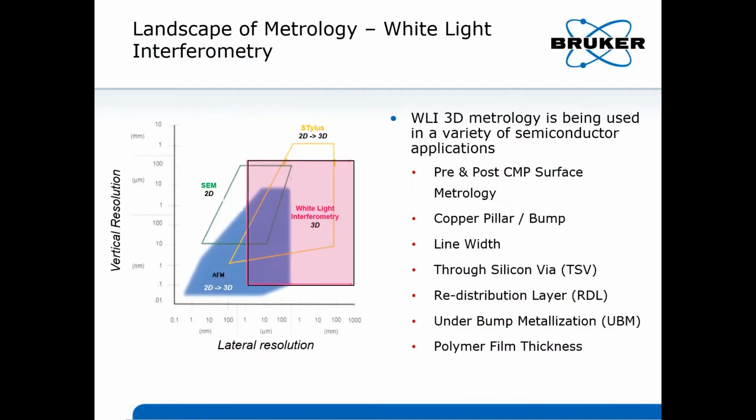So to finish with all those attributes, the white light interferometry technique positions very well versus other profiling techniques. If we plot the vertical resolution on the y-axis and lateral resolution on the x-axis, on logarithmic scales, we can plot out the space where atomic force microscopy operates, as well as white light, SEM (scanning electron microscope), and stylus profilers. So what we see is that SEM, in essence, is great for a certain space, but only allows top view 2D type.